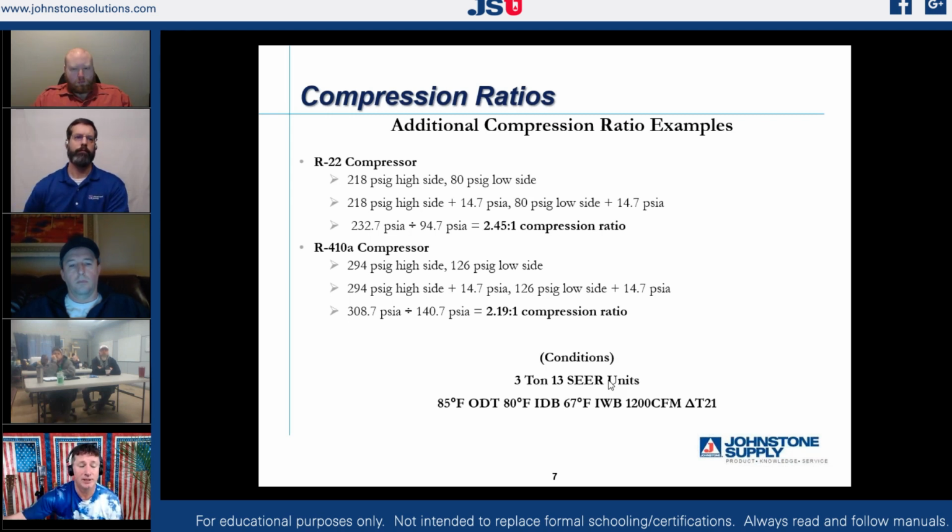I have two identical systems operating with different refrigerants. I take a measurement of my pressures and find out that my compression ratio is lower on the R410A because of the ability of that refrigerant to transfer heat properly, right? What does that tell me about what's going on inside of my vapor pump? Working as hard. It's telling me it's not working as hard. That's exactly right. So if my vapor pump is not working as hard, what does that tell me about the motor that's driving my vapor pump? It's using less energy. That's exactly right.